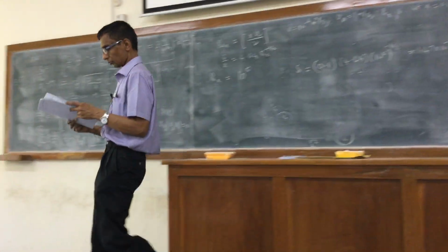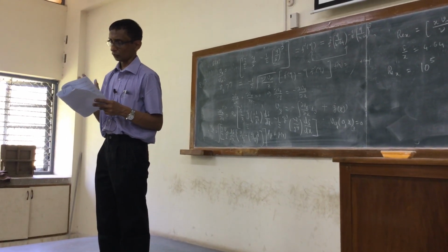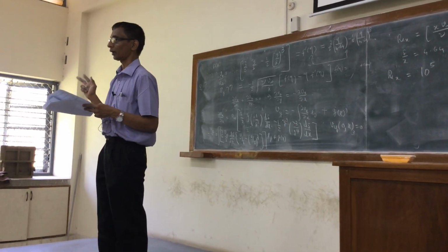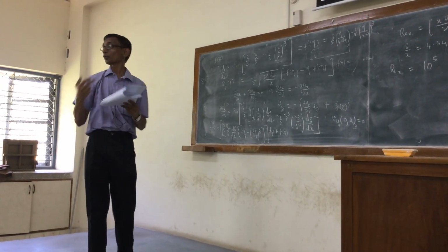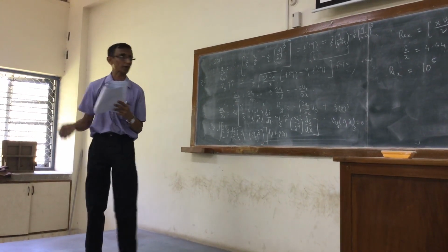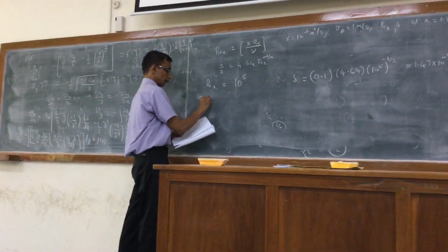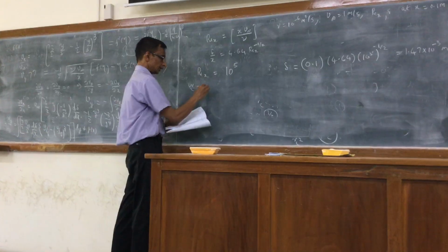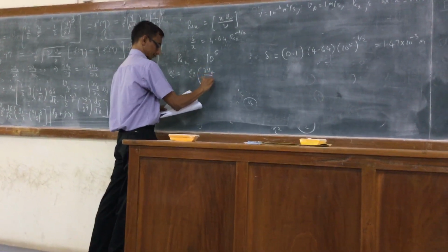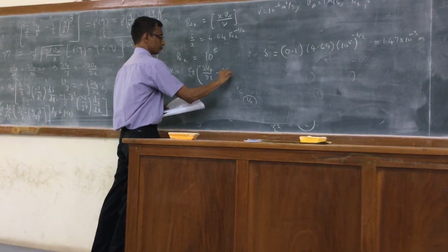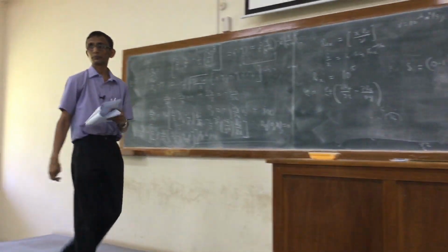Okay. So the main calculation is also the vorticity you are asked to calculate. So clearly Vx and Vy are the only non-zero components, and they are dependent only on x and y. You can easily verify the vorticity vector would be given by Ez times dvy by dx minus dvx by dy. This is what you have to calculate, right?